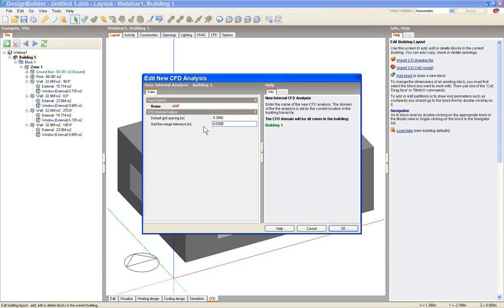What it can do is, when there are very small grid sections, it will merge those together just to make the grid more uniform. And it's important that we have a uniform grid because one of the biggest problems in getting a solution is the accuracy of the grid, and the best way to address that is to have a uniform grid.